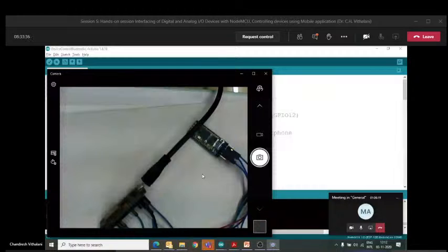So this is how you can connect your smartphone with a NodeMCU through a Bluetooth link, and within a home the Bluetooth will work for a short distance. Here we are not using any internet, we are not using any kind of cloud. It's just a local connection which we are using. We can't say that this is IoT because we are not taking help of any internet.